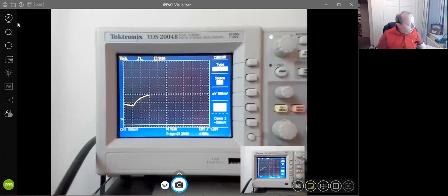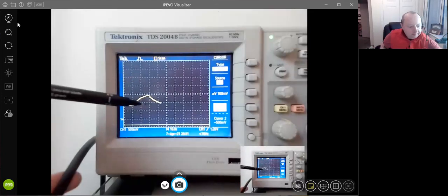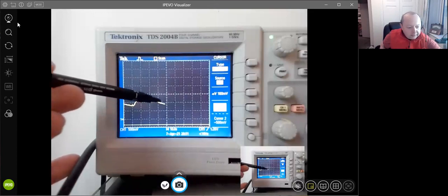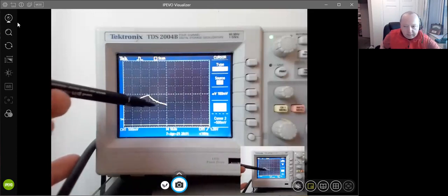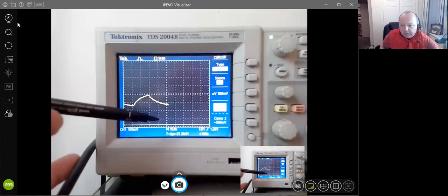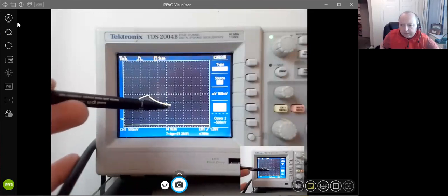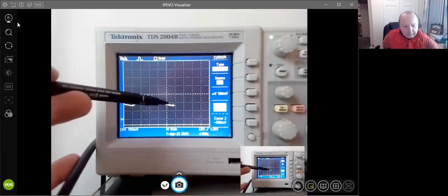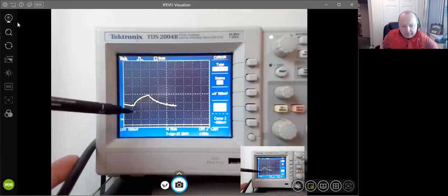Right, and now I'm going to let it cool down. Now the ambient temperature is clearly not at 400 degrees around that sensor. So what we're seeing here on the oscilloscope right now is this is it warming up. And this is latency. So the package has actually got quite a lot of energy stored inside it. So for fast transitions in temperature, this isn't really going to be very useful for us.